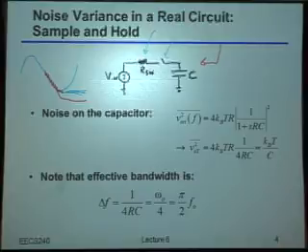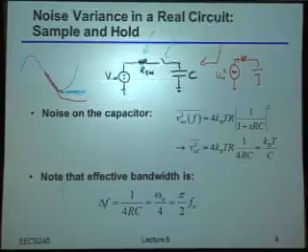Okay, so if we calculate this exactly, then if we follow our standard procedure, while the circuit is on, we're going to have a very similar situation to what we drew before, which was some noise voltage from the resistor, some resistance, and some capacitance, and of course at the end of the day, we're going to measure the output voltage over there. Okay? Well, we already know that the noise voltage density is just 4kT times R, right? That's pretty easy. And we also already know that the transfer function of this, in terms of voltage to voltage, is 1 over 1 plus sRC.